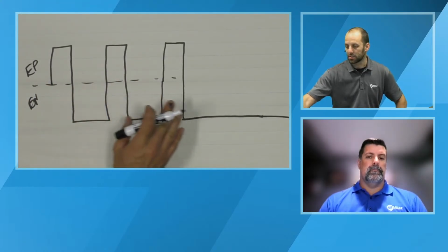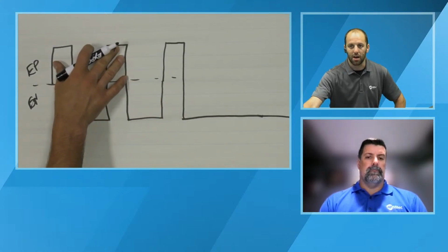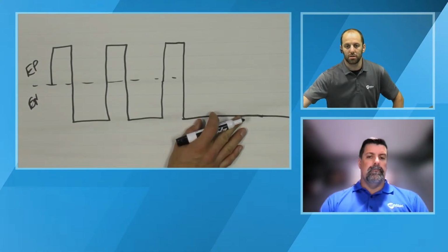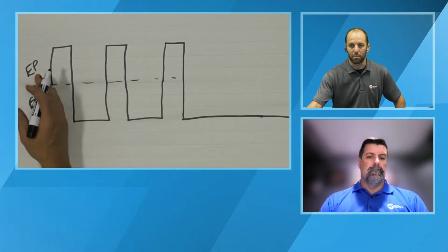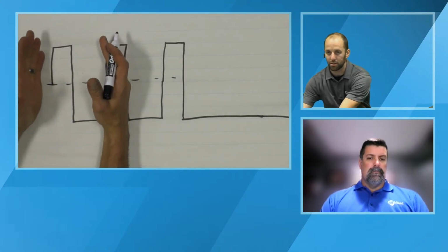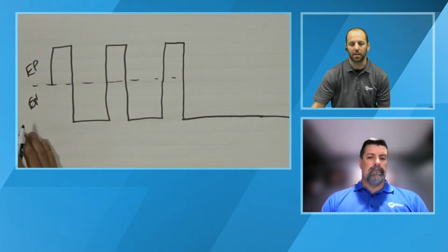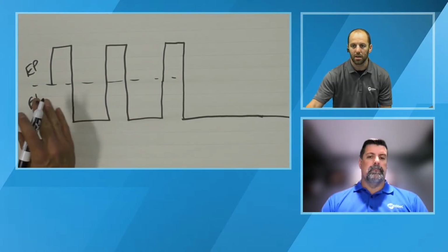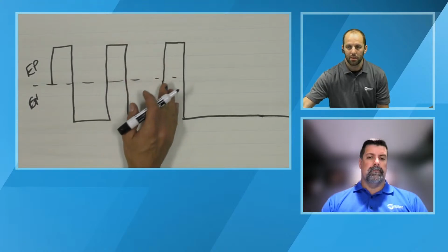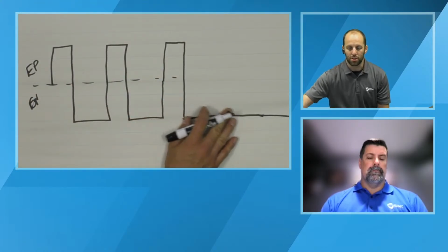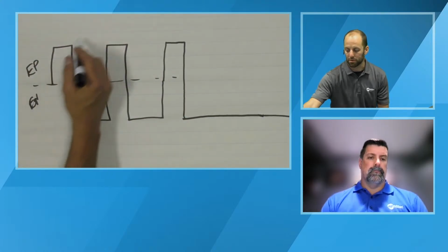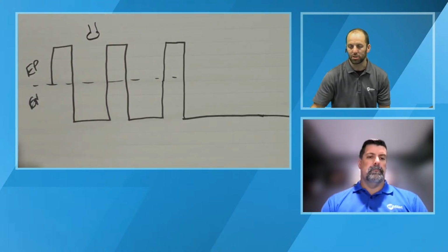And what that does is it allows us to take away heat off of the tungsten and get periods of penetration, because this is happening, you think about 120 hertz, this cycle here is happening 120 times a second. And so if you think about how fast you're traveling as a welder and how far you're going in 1 second, you get an adequate amount of cleaning and you get all those oxides off, you can theoretically do some electrode negative and get heat into the part without creating that bald portion or that tungsten degradation if you're undersized in your tungsten.